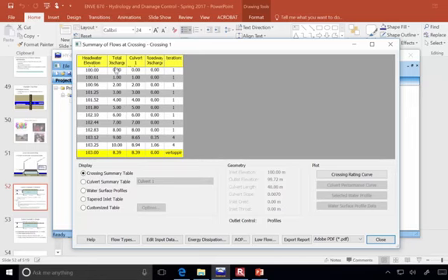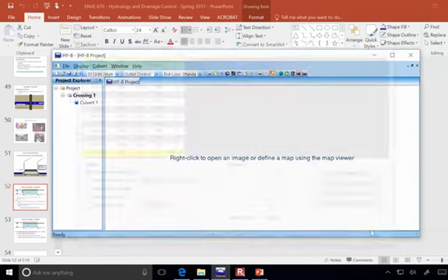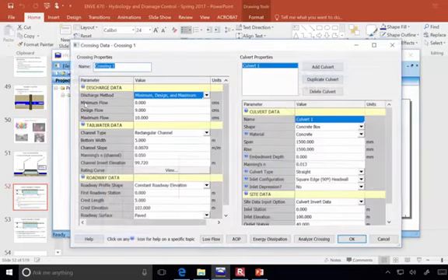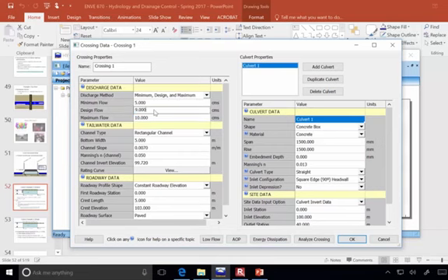So what I can do to nail things down even better is I'm going to have it redo the simulation over this range. I'm going to have the minimum flow be 5, and both the design and maximum flow be 6, and that way I'm forcing it to do those calculations and prepare that table just within this range.